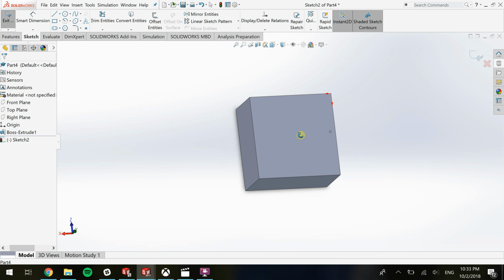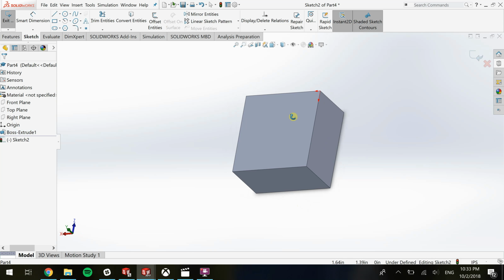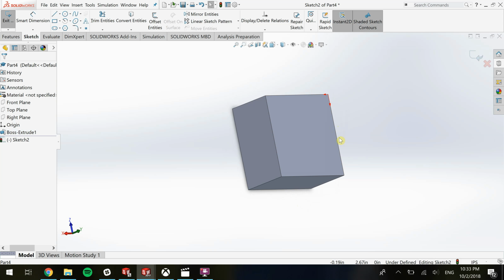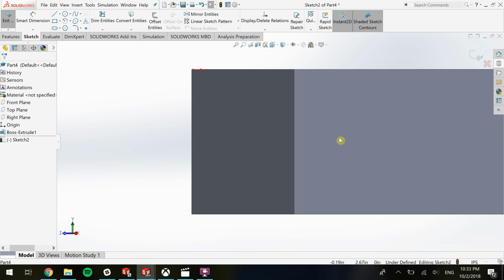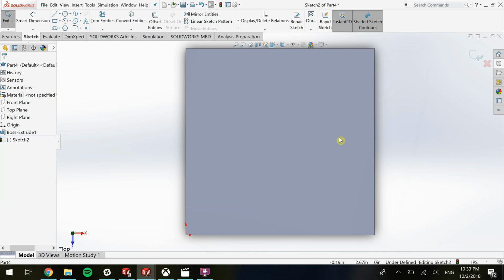But since I'm at an angle, there might be optical illusions. It's hard to get it straight on. So one good tip is you can use Control and numbers. So Control 1, Control 2, Control 3, it shows the different faces. Control 5 is the one we want in this case. I usually just click a bunch of numbers until I find the right one by looking.